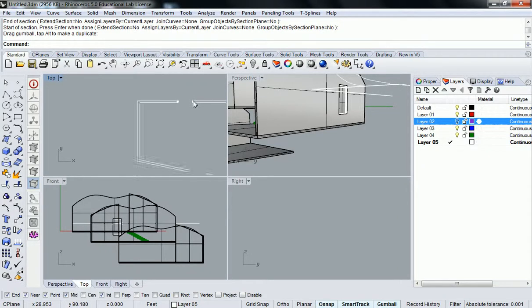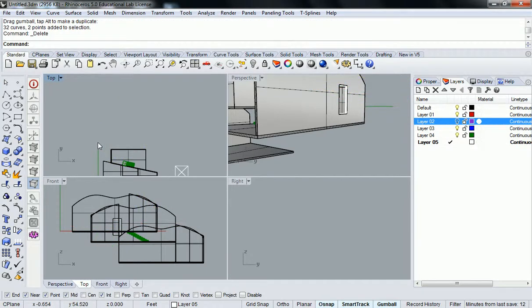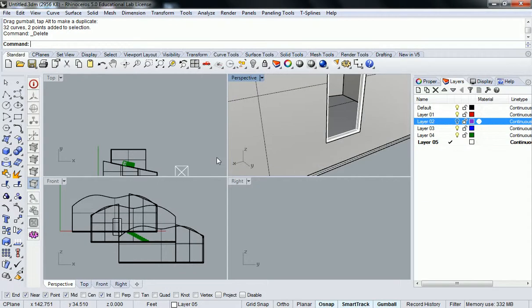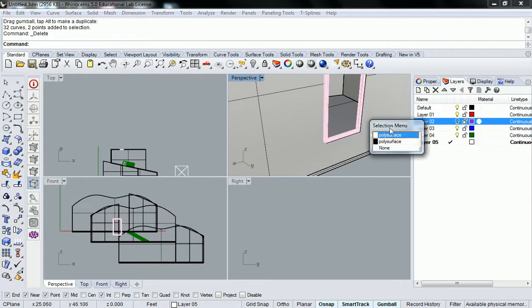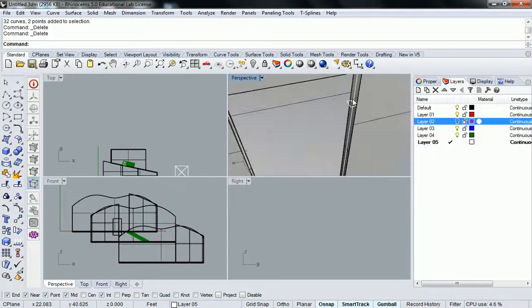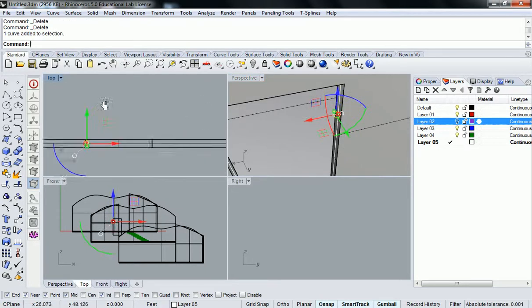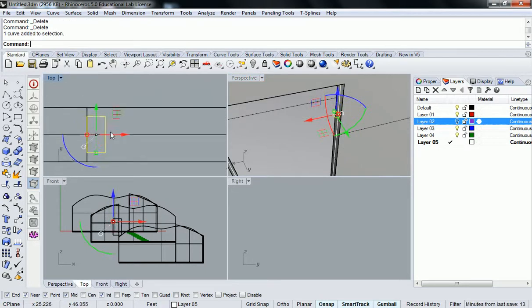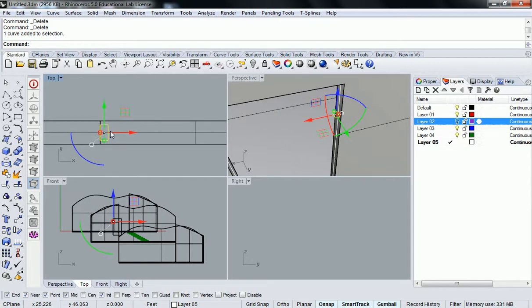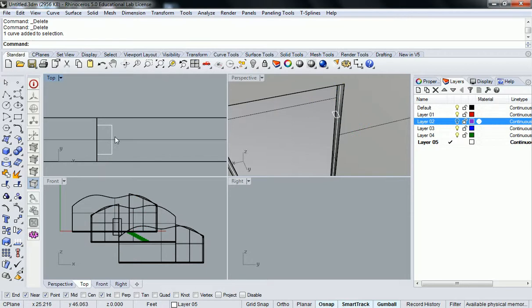And when you get to the point of actually modeling the glass panes, then you know it's even more complete. Okay, so it's as simple as changing the profile if you want to do something different. So you can just edit that profile. Let me anchor something on that. So if you wanted to do, for instance, like a double hung, then you could just change that profile and create a recess for it to socket into.